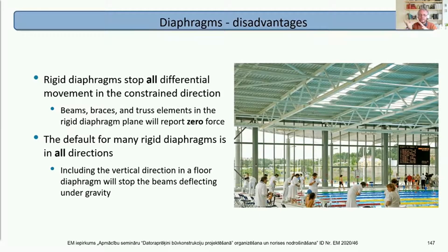And if you are doing that, then the diaphragm may be there for stability. You'll need to calculate the top boom forces independently, separate model, whatever. Watch out for that. Do not go, oh, there's no load in the top boom, I don't need to put any section in there at all. No.